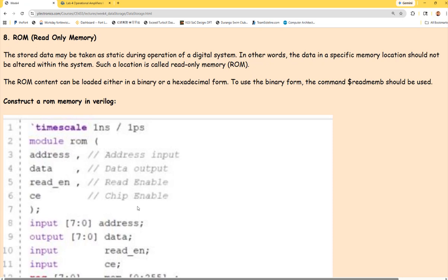And it will be able to convert your assembly code into a ROM file. It's a ROM.v file. It's going to be a memory file in Verilog and contains all the machine code of the assembly code, and also some Verilog structures in there to put all the assembly in. So it's not this tutorial, but the tutorial later. So that's how you put your software, the code, into your hardware.